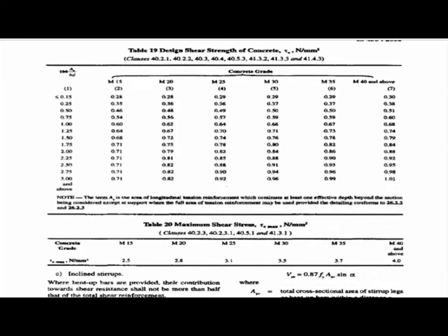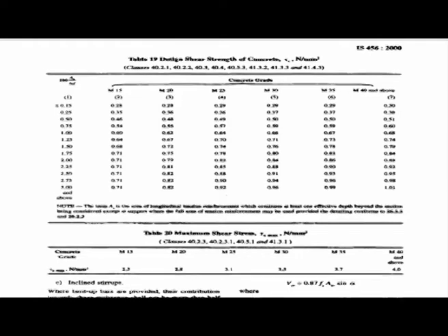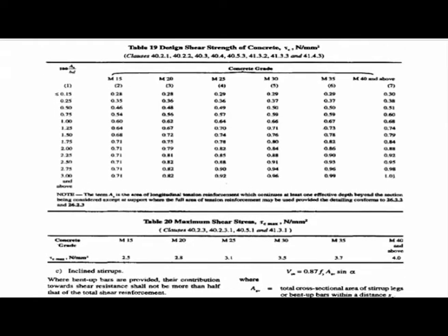This is available here, because I thought I should show you where it is available in IS 456. That should be known to you also, because these are the tables we use extensively. Table 12 we have already discussed, Table 13 we have already told, and another table, Table 19. Now, one more table we shall use, for design of slab, the two-way slab.